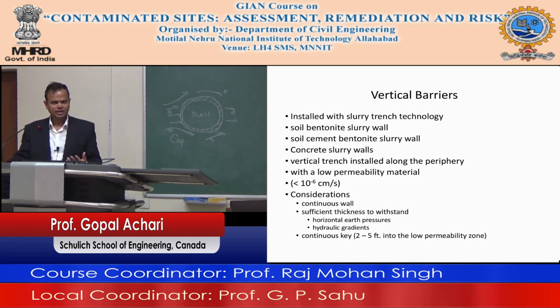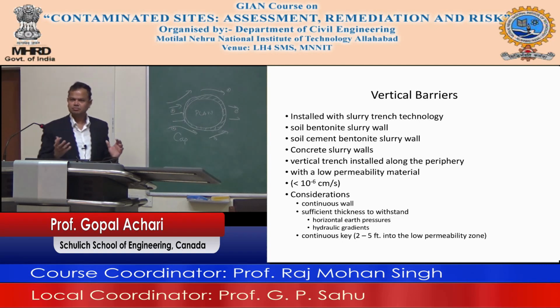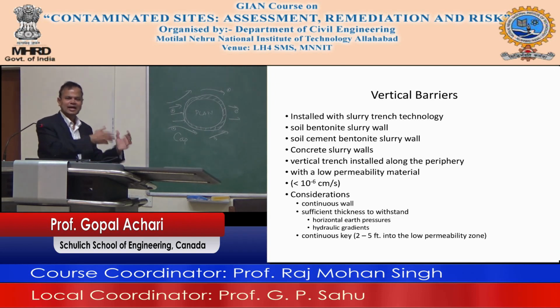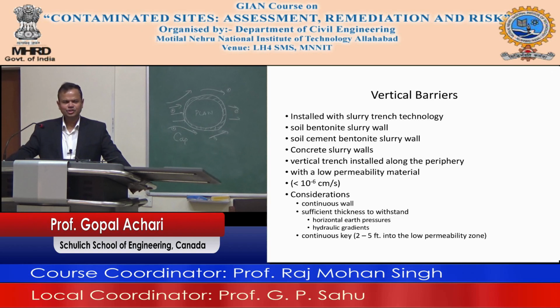It does not allow permeation, right? So it's a very high swelling clay. High swelling means all the pore spaces are occupied by the soil and the water that is held. So use that feature of bentonite. You take bentonite, you mix it with water, let it stay for a period of time, and then you mix it with soil.